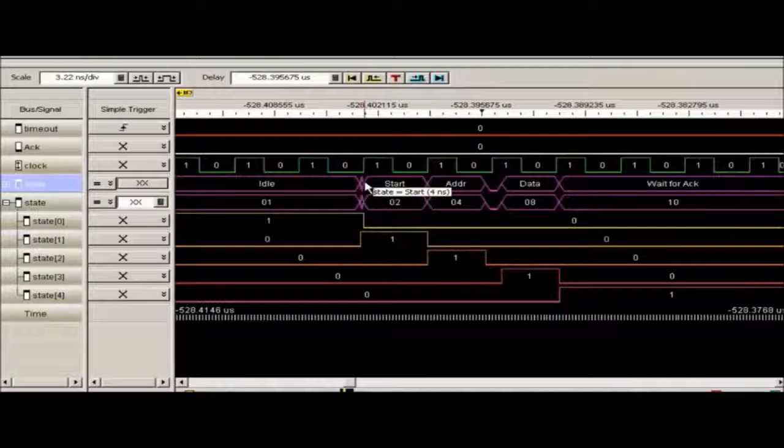And it turns out this design did have a mistake in it. The user constraint file was not set for the Xilinx Zynq 7020 design, thus causing the clock to line up with the transitions in the data. We've found the root cause of failure.